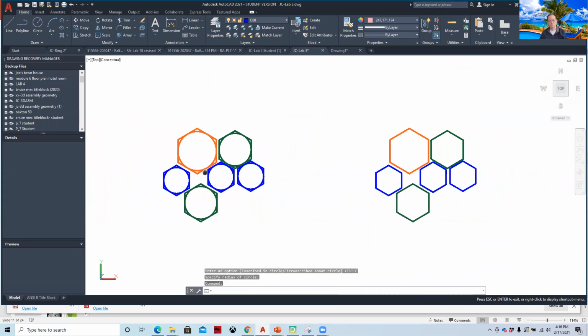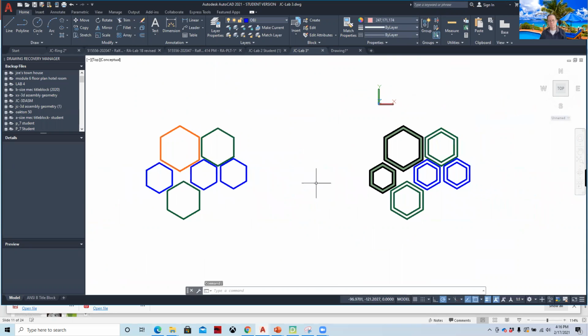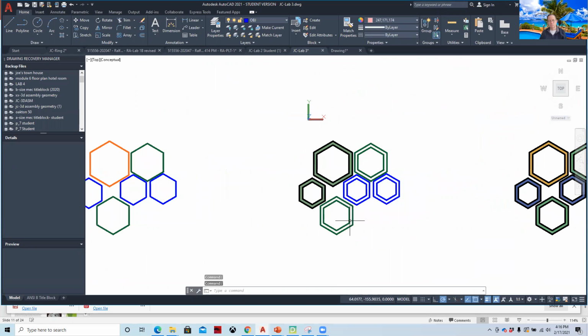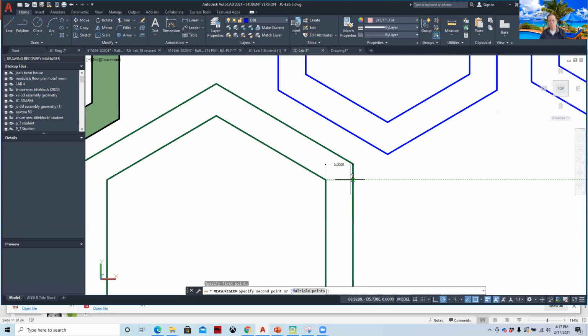And so I've gone and done that. And then I removed the circles because I wanted the inside shape to be the same as the outside shape. And then once I had done that, I offset so that we would have the ability to extrude that. And if I want to look at how much we're extruding those, 5mm thicknesses on the walls.